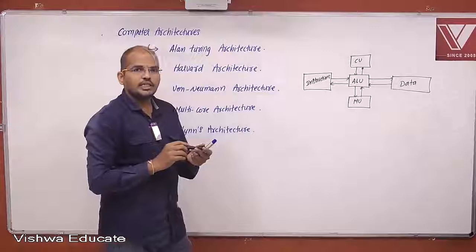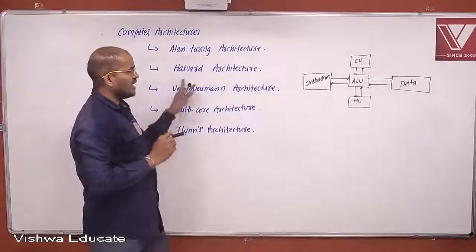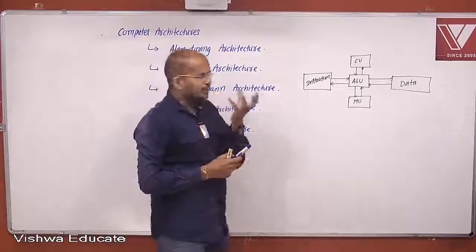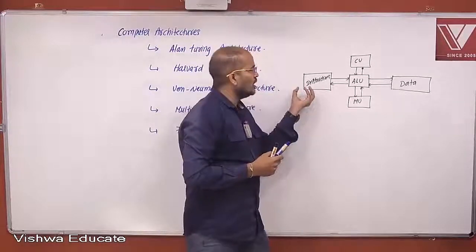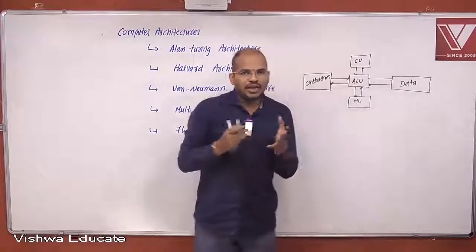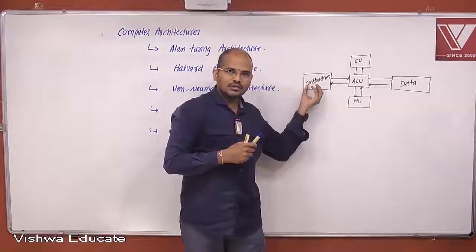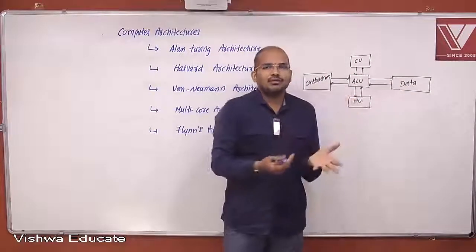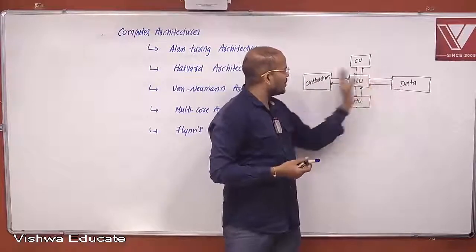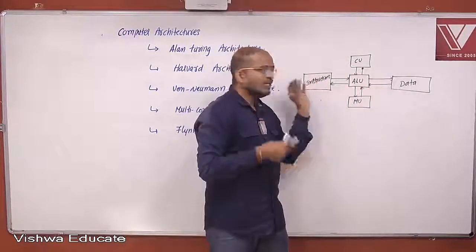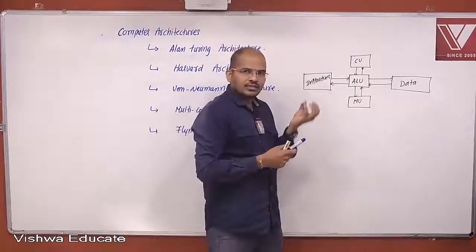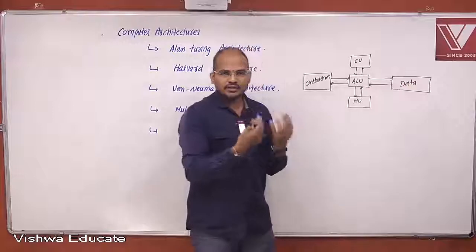So this is basically the Harvard architecture, and the beauty of Harvard architecture is we have separate space for instructions to be stored and separate space for data to be stored internally, and you can handle instructions and data at the same time because you need to have them separate, right? So in this aspect you can handle them independently.